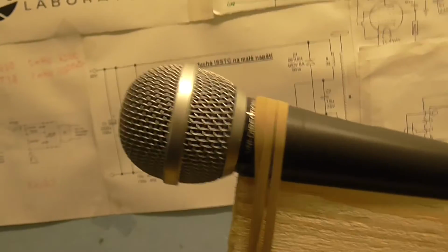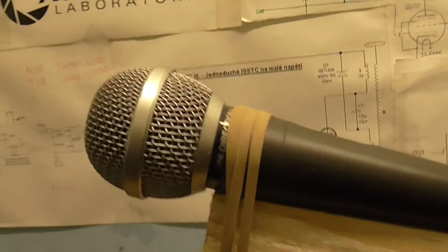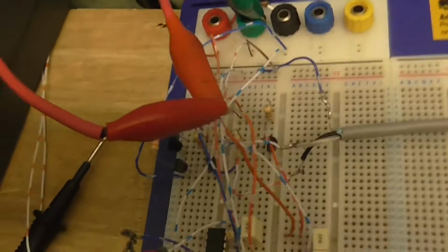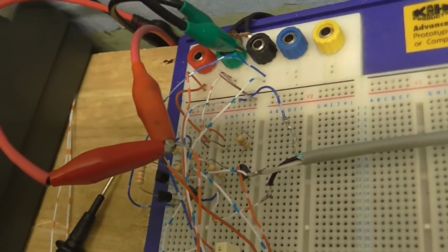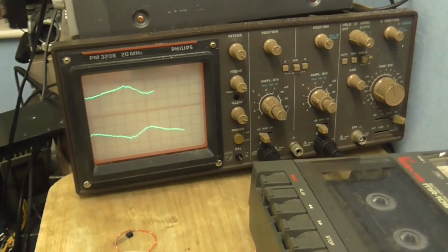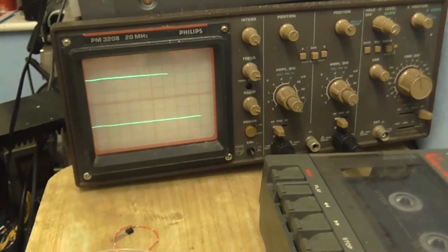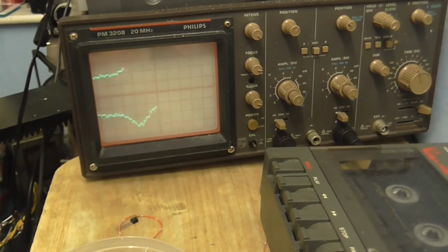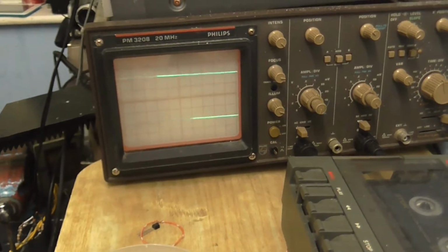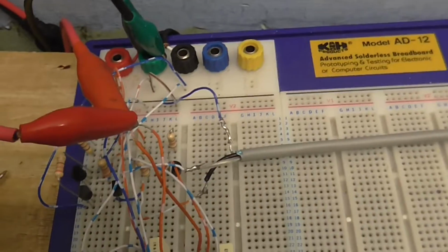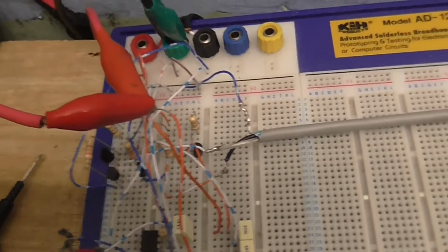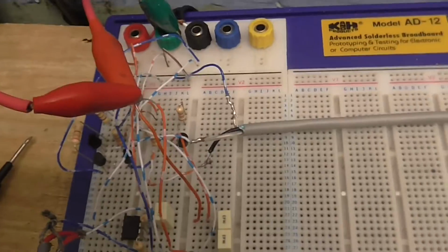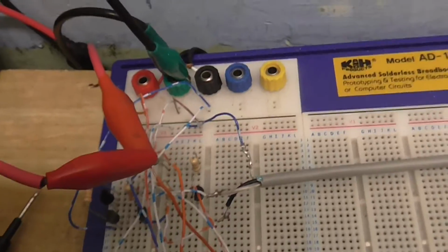So I've got the microphone, excuse me, and that right now is hooked up to the differential input stage, and the output of the differential stage is connected up to my oscilloscope, so I can see the waveforms coming out of it. And as you can see, when I speak, we get opposing waveforms on the scope, like we should do. And even if I have the microphone just plugged into one side of the differential amplifier, we still get opposing waveforms, just like we should do. So that part I know is working absolutely fine.